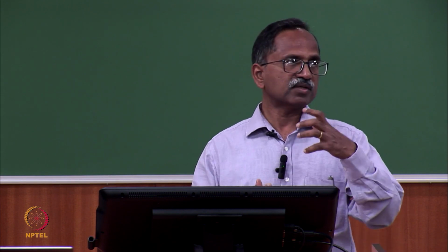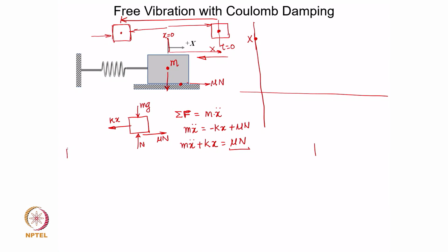That deflection is going to be a constant value, and what will that be? Compare it with what we discussed for a vertical spring mass system. The gravity created a static deflection which was mg over k. So, when this body is hung from the spring and subjected to the gravity load, the deflection delta that we wrote last time was the force mg over k.